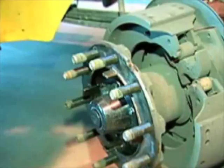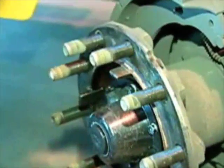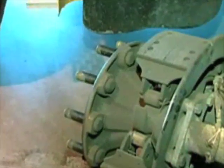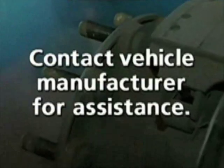If the hub is pilot-centered, you will need to check the runout of the hub pilots with either a special dial indicator or a press made to remove the studs to avoid damaging the hub. Because of the specialty of these items, we recommend that you contact the vehicle manufacturer for assistance.